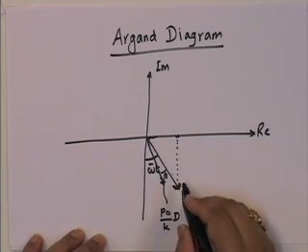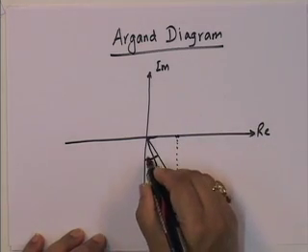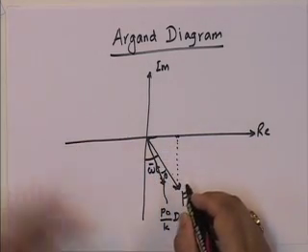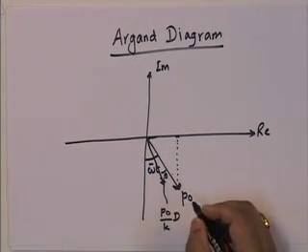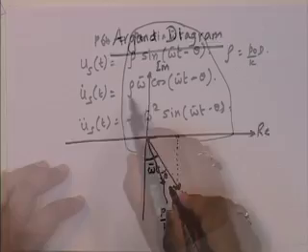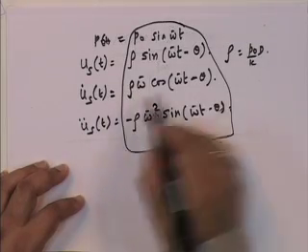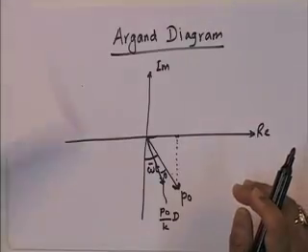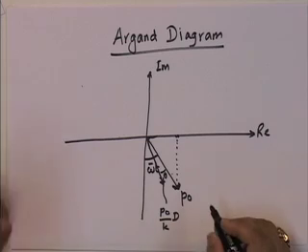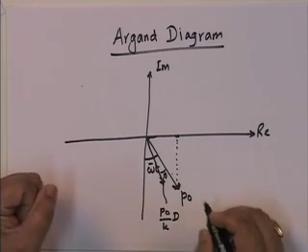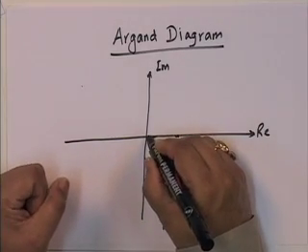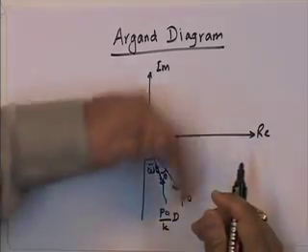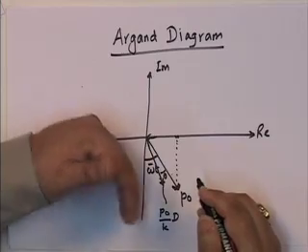So, displacement is this direction. If you look at this, this is omega bar t minus theta, and if you take the same thing, you will see that this is indeed P naught d upon k. So, this is the displacement. This is P naught d omega bar upon k cosine. Now, how does cosine look? Cosine, if you look at it, actually leads. It always leads. So, it is leading. See, this is lagging, this is leading.